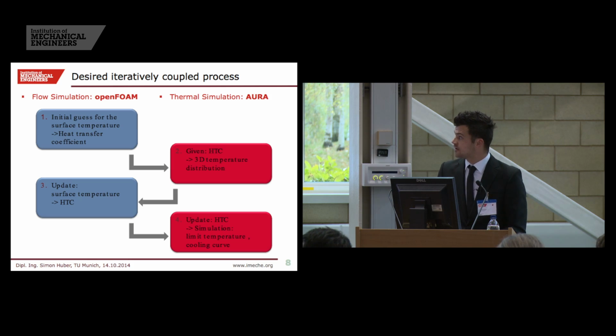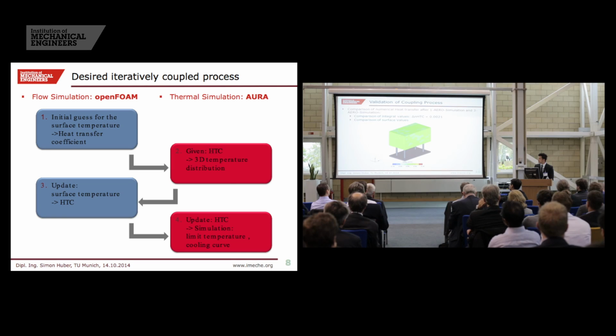So to validate this process, I am comparing the heat transfer coefficient on the cube after the first and after the third CFD simulation, and we can see here that the integral values vary by 0.2%, and also the distribution on the surface, which you can see here, is barely visible. So the coupling process like this is enough, and I need no further coupling.